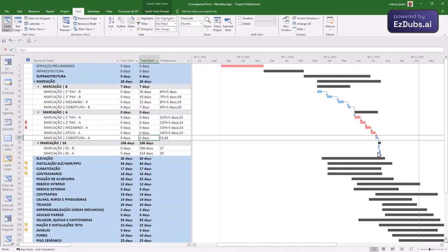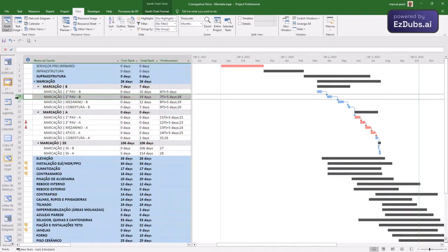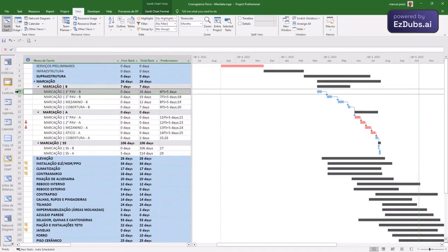What is the idea I am going to try to bring here? In principle, the distance between one activity and another is the free slack. How much can it be postponed without disturbing the start of the next one? The problem is that there is not just one connection between the activity and its neighbor. There may be other connections that do not appear in the drawing. So, the strategy of placing the activities that happen before the last one as late as possible and using late as possible, all free slack would be reset and all of them would be placed at the end without disturbing the last one.